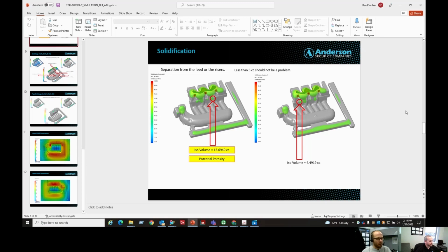Okay, so this is all in an effort to troubleshoot any potential problems that could happen at the foundry, ahead of having the physical tool. Yeah, the biggest advantage of solidification is to get you much closer right out of the gate. It's not a perfect science. It is left to interpretation a lot of the time. But the biggest reality is, do some solidification simulation up front. It saves you time and money later on for revisions that you would have already accounted for.